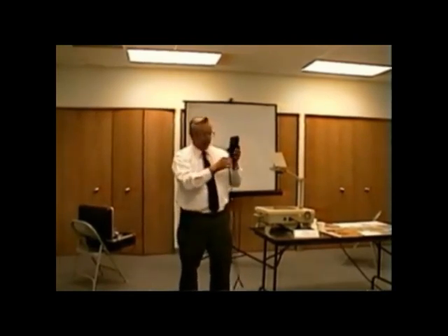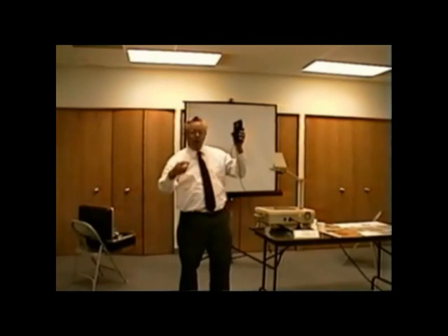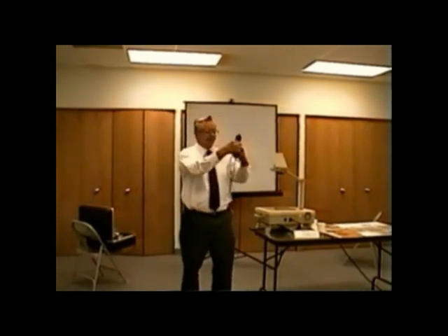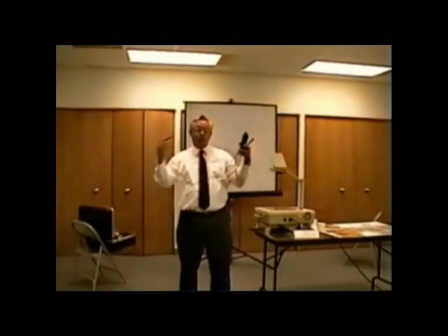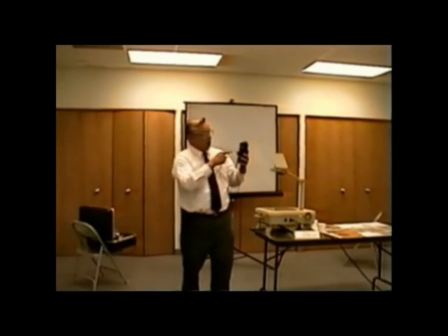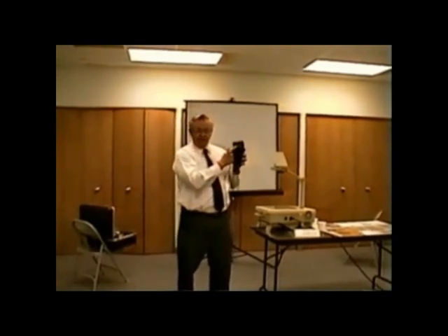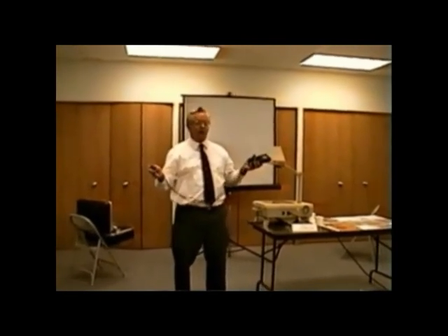I took the wire off the flame sensor, and because it's an amp meter, I took the one wire and I put it on the flame rod, and I put the other wire on the wire that was on the flame rod, and I lit it up. And that's in series, and that would be an amp meter. And he says, I started it up, and he says, I got 13 microamps. He says, this is terrific. But he says, it only goes on for 5 seconds and goes off.